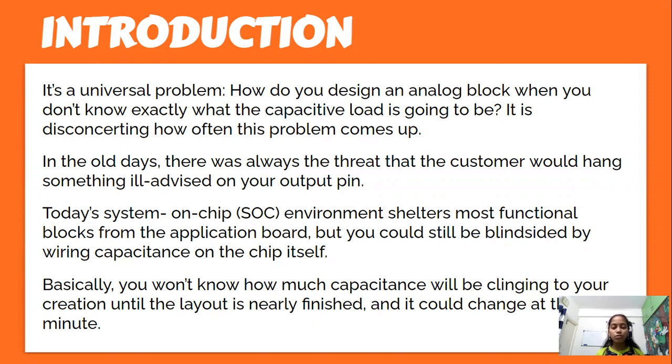In the old days, there was always the threat that the customer would hang something unexpected on your output pin. And today's system on chip (SoC) environment shelters most functional blocks from the application board, but you could still be blindsided by the wiring capacitance on the chip itself. Basically, you won't know how much capacitance will be clinging to your creation until the layout is nearly finished, and it could be changed at any minute.